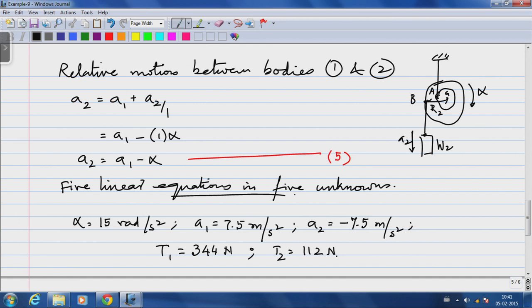I do want to close with one point, that notice that when we applied this Euler's second law to the spool, we chose to take moments about G, which is the center of mass of the spool. If you did not do that, but chose to apply sum of moments equals I times alpha about any other point, you would get an incorrect answer, primarily because you are not guaranteed that those other points of reference are non-accelerating.